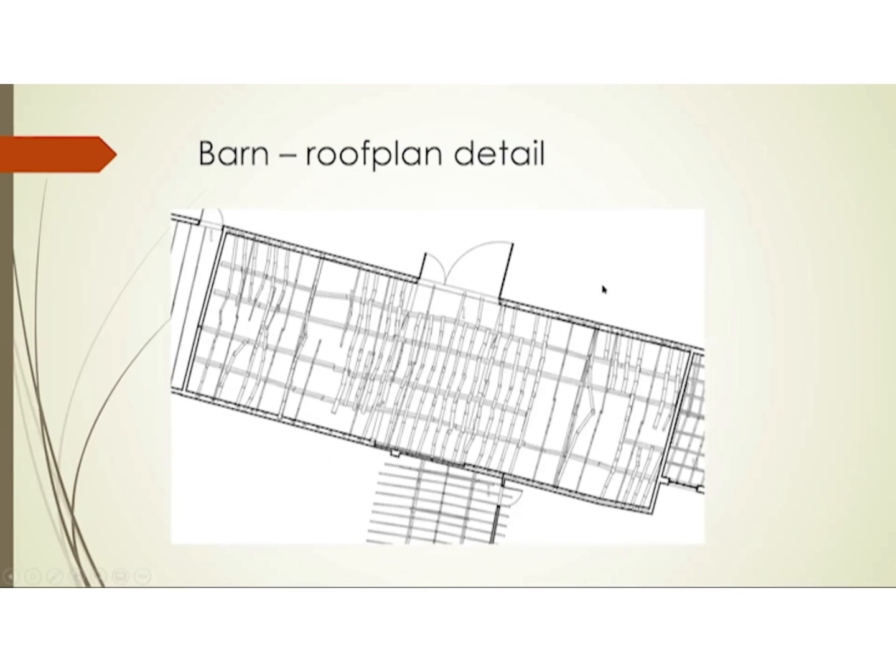I don't know what scale this survey was scanned at, but it is important that you don't design to a scale different to the scale at which the survey was carried out. If the survey is carried out at a scale of 1:100, you shouldn't be designing at 1:50 based on that survey information.